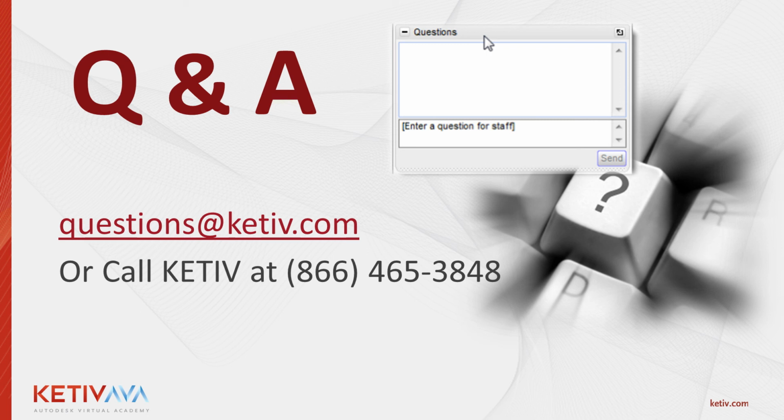Yeah, and to the point of the last question, a lot of Autodesk and a lot of KETIV employees start in VBA, and the syntax is the only thing that changes. So in VBA, you're saying you're calling something and then you're setting it. You remove the set in iLogic, and we can condense that code down by looking at this example. You don't necessarily have to call the name twice, like assembly is this type of object and assembly equals this object. You just say assembly as type equals object, or object equals something. So it's simplistic, but it really is the same API that you would use in VBA and Inventor and .NET as well. So cool. So we got a couple more here.